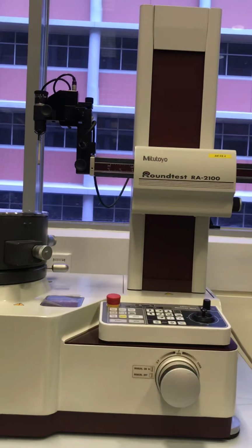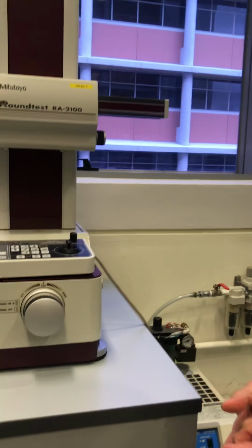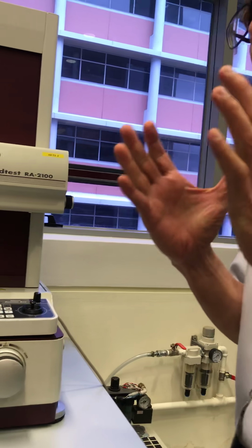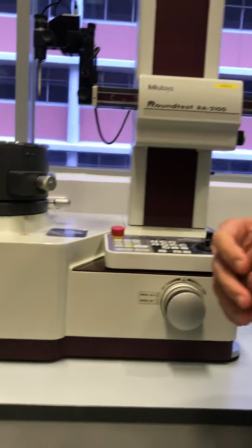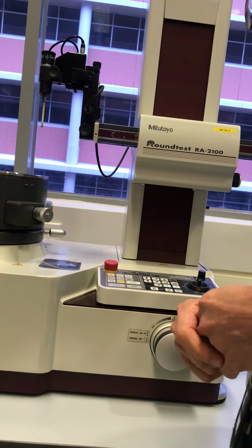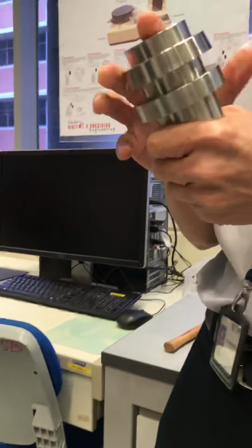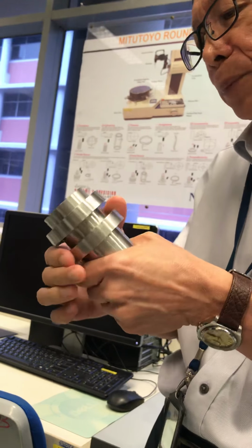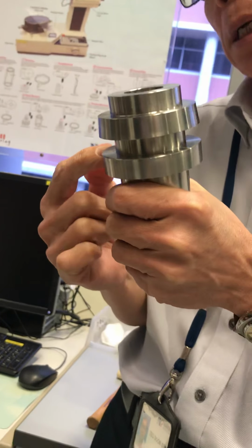Concentricity. So first thing is that you need to understand the drawing. What is meant by datum A? Where's the datum A feature? The drawing will be on about this workpiece. Datum A is this diameter here, which is diameter 68. Datum B, no, there's no datum B.